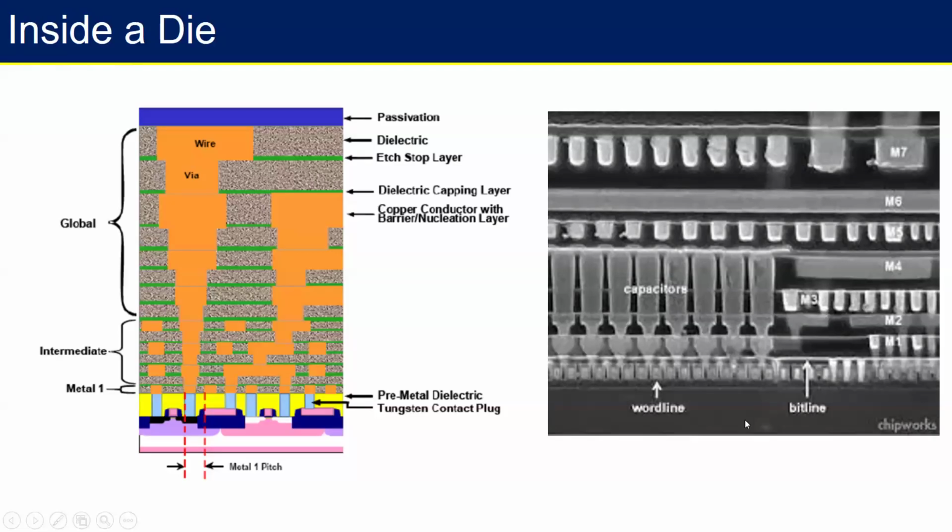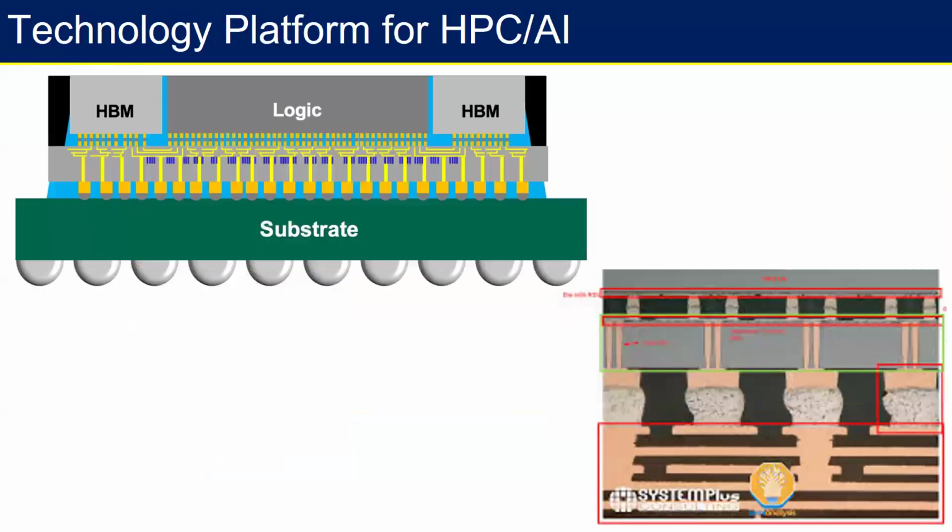But in this, the idea is that IC, word line, bit line, all these things which you see in gray, what are these? This could be your metal on the side, right? So the metal filling which you will have, obviously, this is all metal, gray, and you will see somewhere that these black portions are your dielectric, right? Which is separating these two. So that is how you see so many materials making these systems, what we just saw, possible.